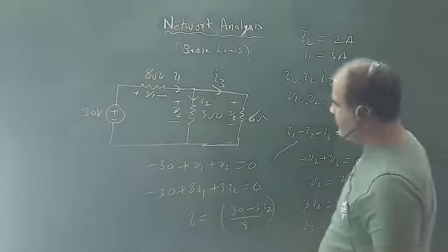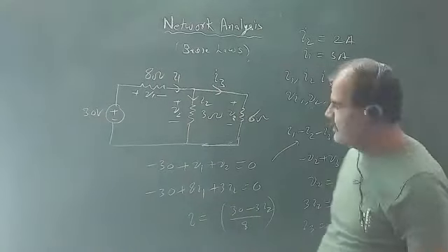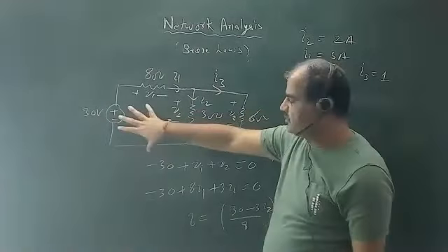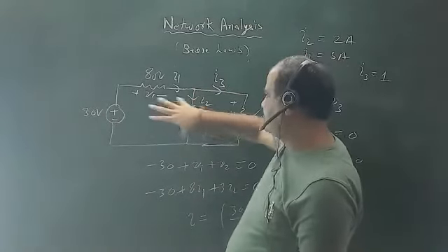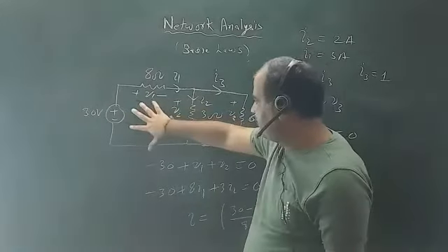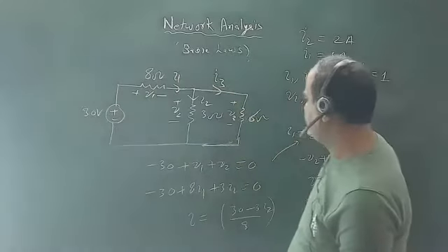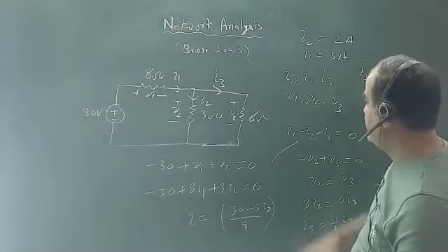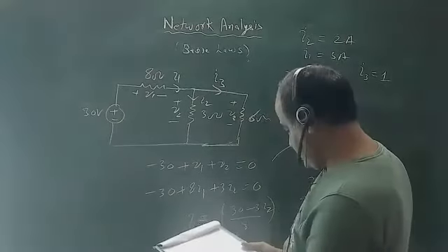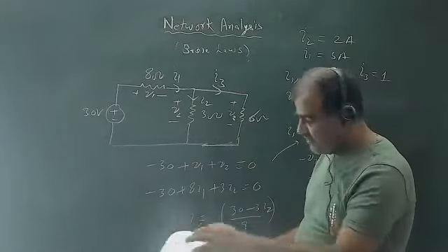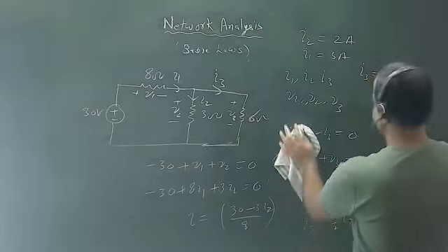So you can choose. If you are comfortable, if you have enough practice of the KVL calculation, then you can solve directly. You find out the voltage, you calculate the total resistance of the circuit, then divide the total voltage by the total resistance. That will give you current. You can do it the other way also, since both these are parallel. So this was for today. I'm giving one homework, so just try that question.